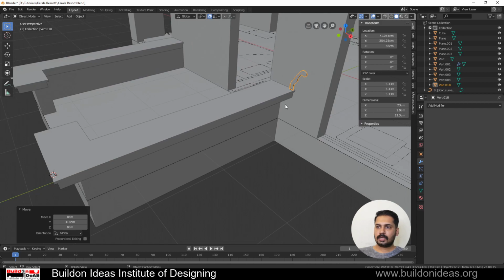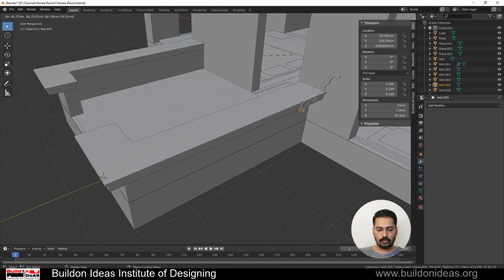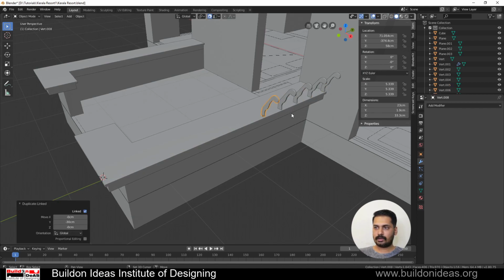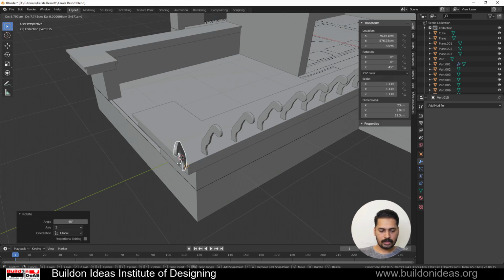Okay, now we'll make a copy of this. In order to do that, just select this and Shift Alt D, and then move it in a Y direction to a point like this, and then give Shift R to repeat it until you have something, and then rotate in Z by 45, minus 45. Just move it in Y once again just to position it.